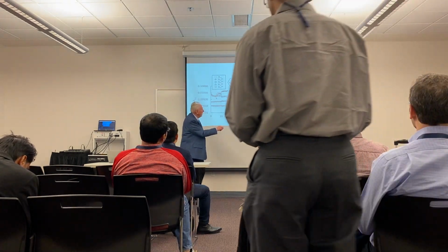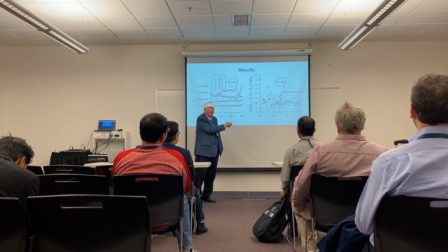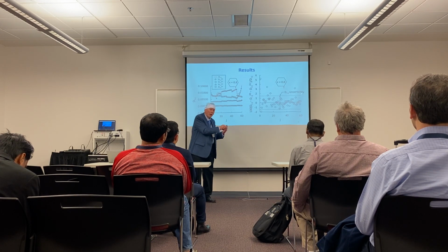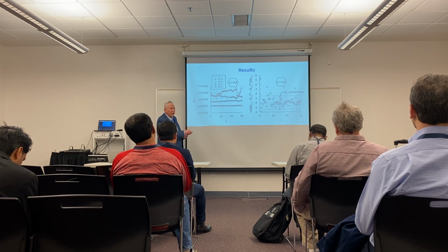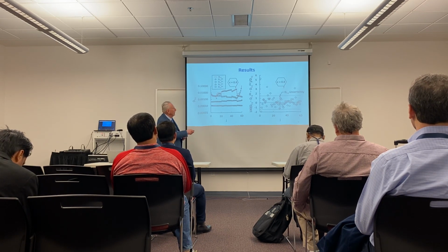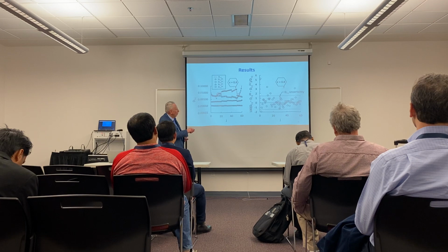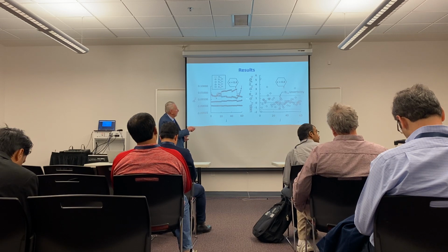And the error is generally limited to the uncertainty in the original Dij calculation obtained using the Monte Carlo ray trace method. So you can actually predict an uncertainty in a Monte Carlo ray trace. And the uncertainty for 60 million rays in this case is plus or minus 1.5%. So our estimate using only 2 of these contributions, these first 2 here, is pretty good.